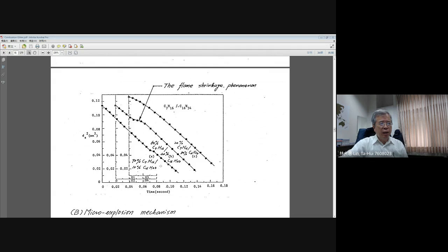But here they show you a sharp change of your droplet. That means in these regions, since most of the C7 has already evaporated, you need to face a larger amount of C16, which has higher than double the boiling point. Then you need to wait for heat sufficient to increase the temperature to meet the boiling point required for C16 gasification.